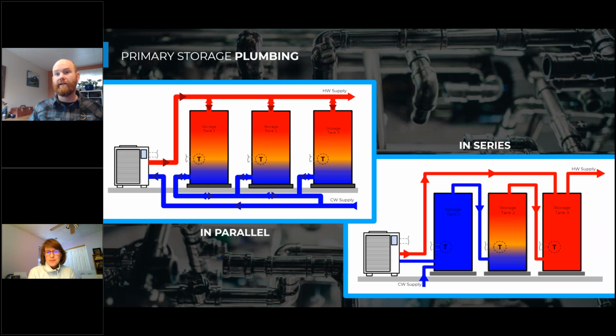Typically our pipes are insulated, or they should be insulated, and so that insulation should prevent that solar gain on the pipe, which would heat up the water and cause already heated water to the unit. The primary way that you push already heated water to a heat pump is in the temperature maintenance system, because with the hot water circulation temperature maintenance system, we're discharging about 120 into the hot water piping, and then we're pumping it back at a slow rate so that it maybe comes in at 110 degrees Fahrenheit.